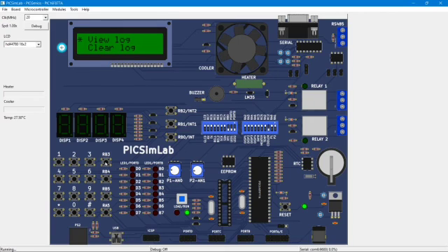By entering the correct password, we will get into the view log screen option or clear log option or change password. To navigate these options, we use the RB5 switch, RB4 and RB3 switch, and to select an option we use the RB5 switch.